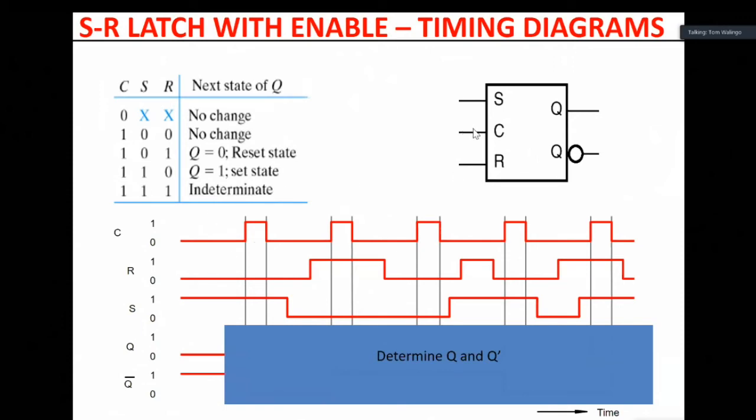If you check carefully, when the clock is 0, during these points of zeros, it will be in memory. That's the first thing. When the clock is 1, it behaves like a set-reset latch, which is active high. So let's start here. The clock is 0. Whatever you started with will remain.